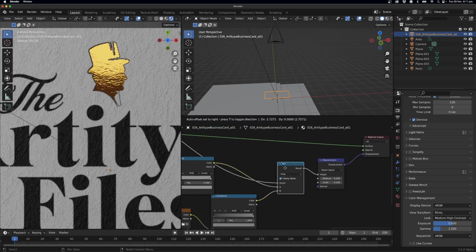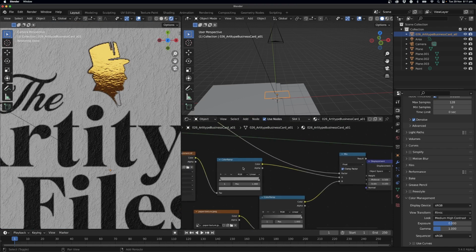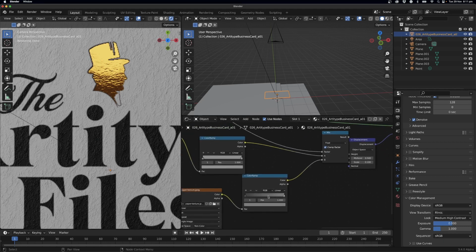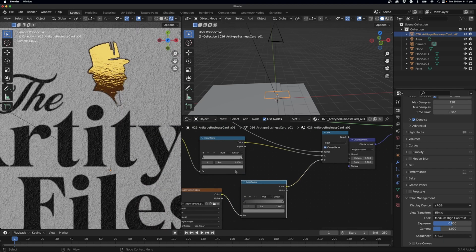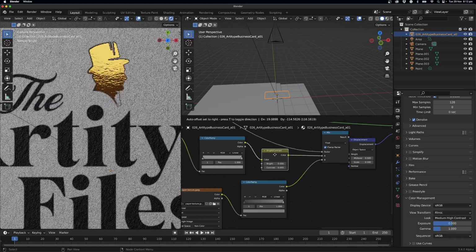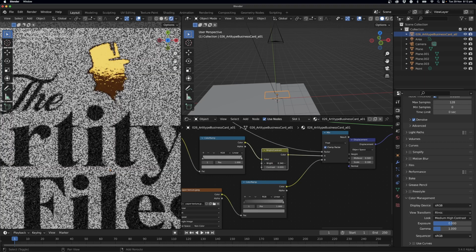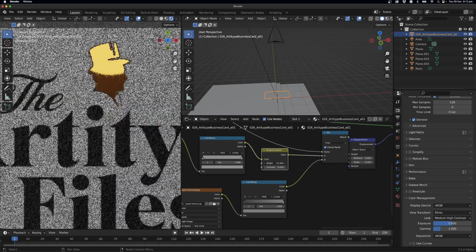The way we can fix that, if you want it to work the same, is to do with the displacement map, and it takes values, so anything above black will be displaced and raised. So what I can do is these two are different sets of colors, and I can just add in a brightness and contrast, drop that one onto the displacement, and we can either push the brightness up, so keep pushing it up, or bring it down.